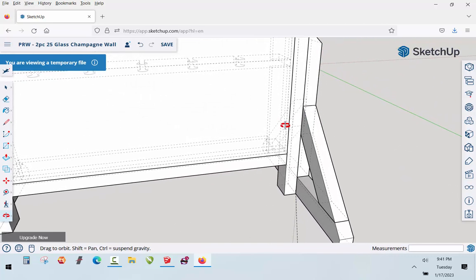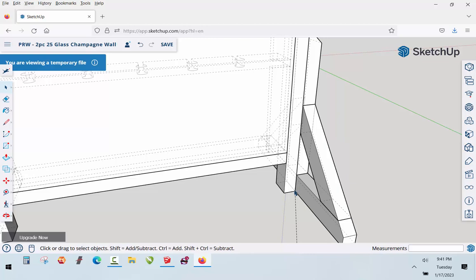So I'm just going to turn this around a little bit, because we were grabbing the dimension from here and coming at an angle up to here. And so what I want to know is from the bottom of this, or really the top, so really from right there to the top of there, what's the dimension? And you can see it's still a little bit of a goofy dimension. And that's because we didn't account for the thickness of our plywood. So now if we come right here, that's the front face of our plywood. That's what that hidden line represents to the top. And we can see it's 11 1/4 inches. So it's a more standardized dimension.